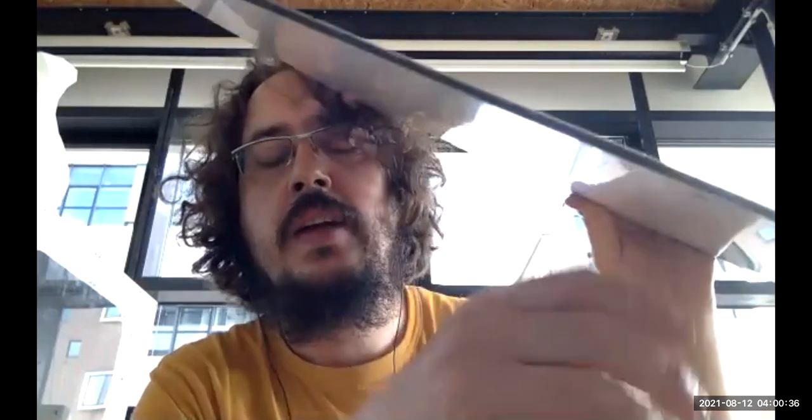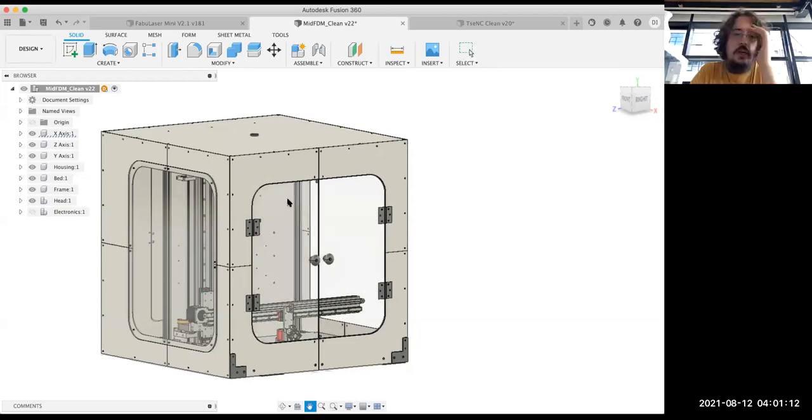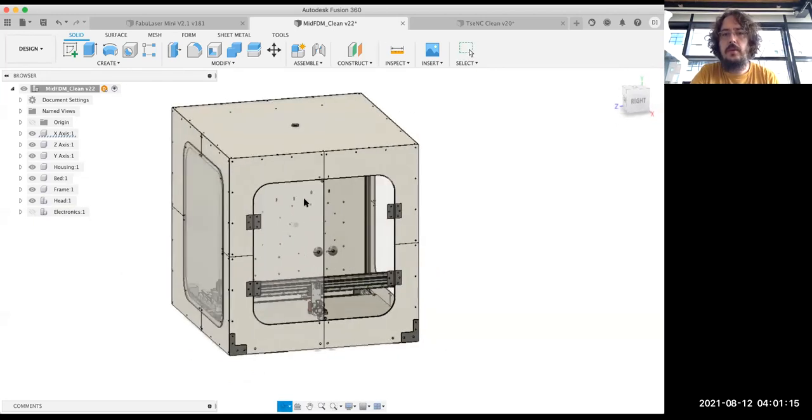So this material, guys, gives you some properties of the aluminum because it's rather strong. It's very strong, for example, in terms of bending, but it's very easy to CNC mill it and cut it with a simple tool without risking that the aluminum will stick to the tool, and it's very easy to handle. It also has some isolating properties, and it's made to stay on the outside. I use it for many housings for my machines now, so I highly recommend you to use this material. So we go back to the CAD. This is the final shape of the machine.